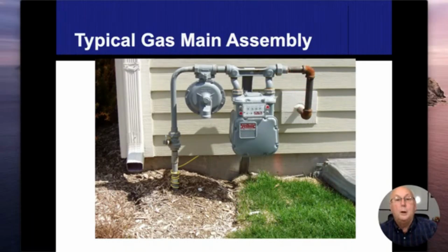So what belongs to the gas company and what belongs to the homeowner, you could see up here is kind of the last part that was painted, this universal fitting. So everything to the right of that that's not painted, that belongs to the homeowner. The gas meter regulator pipes that go down into the earth, that belongs to the gas company. Now, this pipe that we have above ground will be metal, all right? But this metal pipe goes into the earth maybe a foot, maybe 2 feet. It doesn't go far. Most of the gas pipes that we have underground are all going to be plastic, all right?